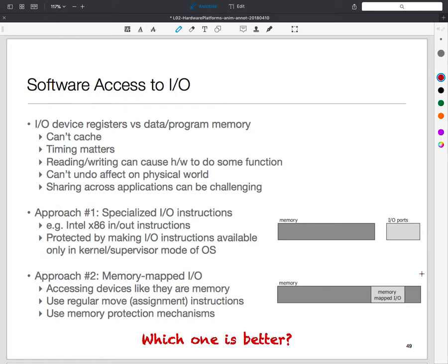One of the problems that we often face is the following. Let's say I say a equal to read from address 0x10, and then again I say b equal to read from the same address. A smart compiler will say, aha, you are reading the same thing again, so it will just scratch out this one and simply set b equal to a. That's mathematically equivalent. But obviously, with I/O devices, that's not correct.